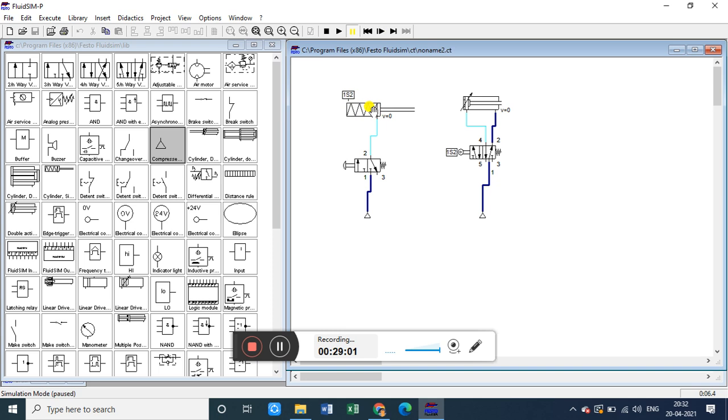Okay, then next step. Now when this piston is moving from 1s2 to 1s1 position, this is 1s2 position, this is 1s1 position of the piston. So whenever this 1s2 is getting unpressed, because of the spring, the right side block will become active. Okay, because the rod end will change its position.